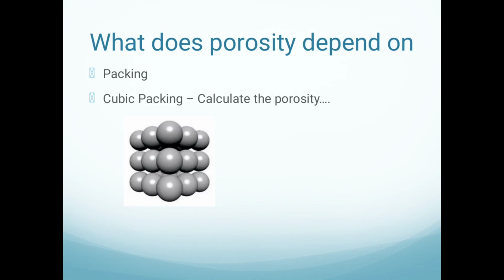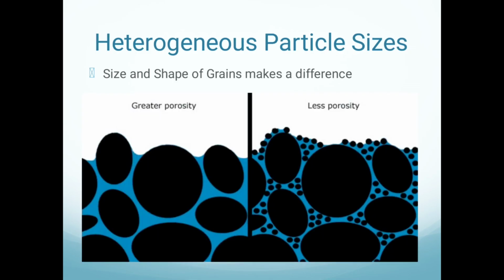Next one, what does porosity depend on? It depends on the packing and cubic packing of the material. Next, heterogeneous particle size and shape of the grains makes the difference. The first one is a greater porosity which has more pore space, so the water will easily get filled, and on the other side the lesser porosity means the water accumulated by this particle will be less.